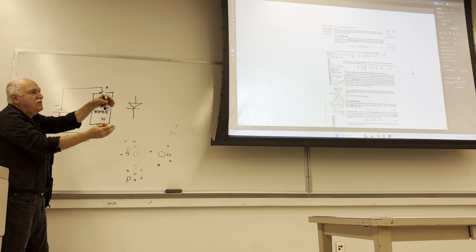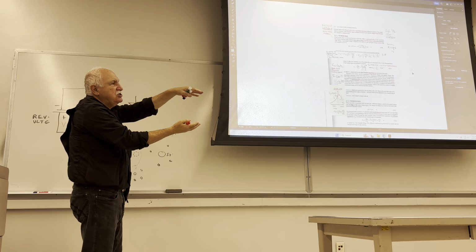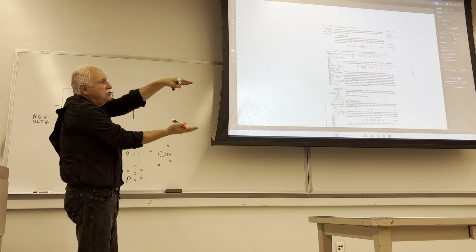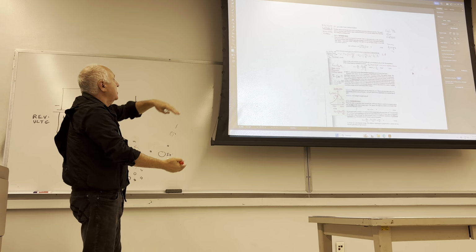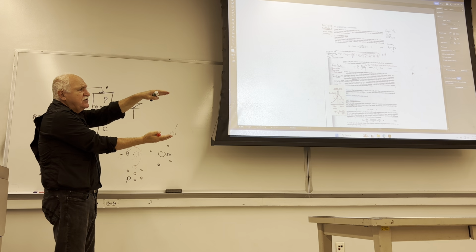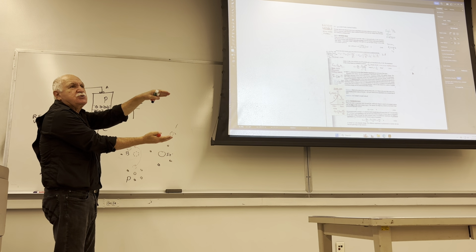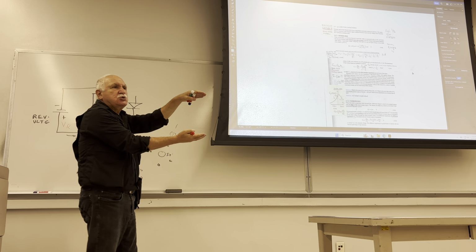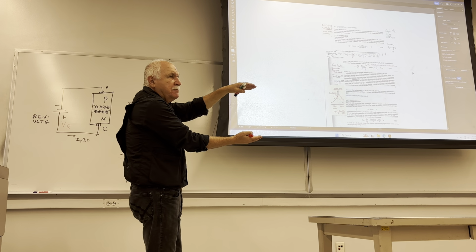So that means you have two plates, basically, positive charge, negative charge, with this much gap between them. If you start parting them, widening them, because of increasing reverse voltage, the capacitance between the two plates will decrease, giving rise to a lesser capacitance.